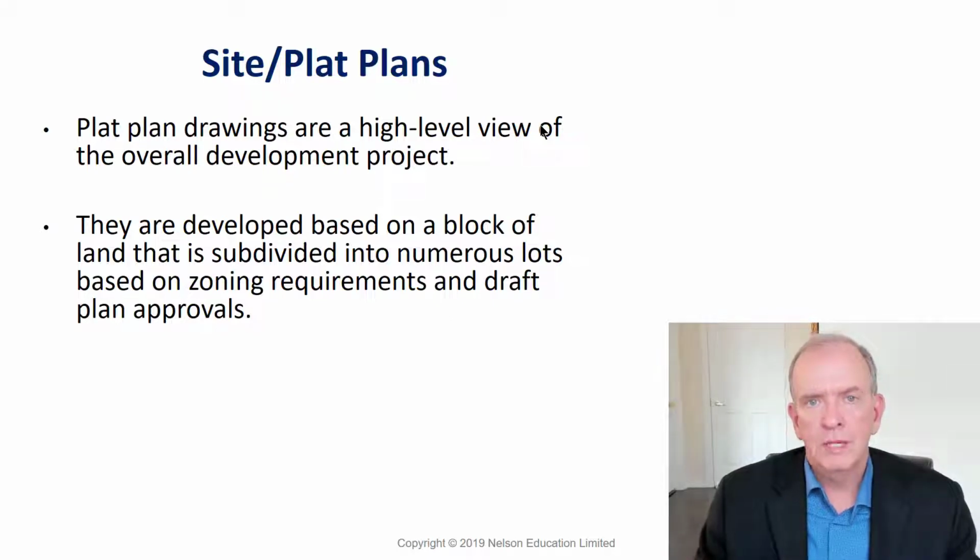The grading has to be done for the streets. We have to ensure that the runoff from storms is going to run in the right direction, and that the sewers are going to have the capacity to carry that water. We may have to have drainage collection areas for really bad storms, until the sewer system can catch up, like an overflow. So all of this has to be worked out. So we call an individual plan a site plan. When it's a multitude of lots, we call it a plat plan.